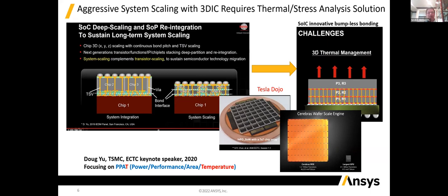In the center is a new design style for SoIC, System on Integrated Chips. We can see an example coming from AMD, which has a V-cache on top of the active die using SoIC. And for vertically stacked dies using SoIC, thermal mitigation in the center of the stack will be more difficult compared to the side of the die closer to the heat sink.